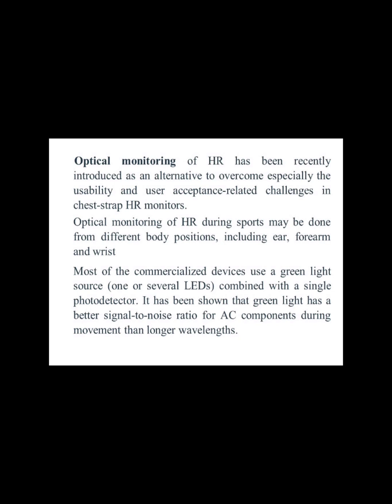Optical monitoring of HR has been recently introduced as an alternative to overcome especially the usability and user acceptance related challenges in chest strap heart rate monitors. Optical monitoring of HR during sports may be done from different body positions including ear, forearm and wrist. Most of the commercialized devices use a green light source, one or several LEDs combined with a single photodetector.